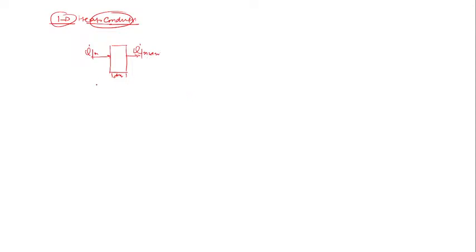And then you can apply the energy balance. E dot in, within the control volume, minus E dot out plus E generation is equal to E accumulation. And since in most of the cases we are talking about steady state, there is 0 here. E in is simply qx, E out would be qx plus dx. E generation may be there. Let's say we are going to consider generation also, then it's qg into volume. Volume is area into dx. Clear? That's equal to 0.